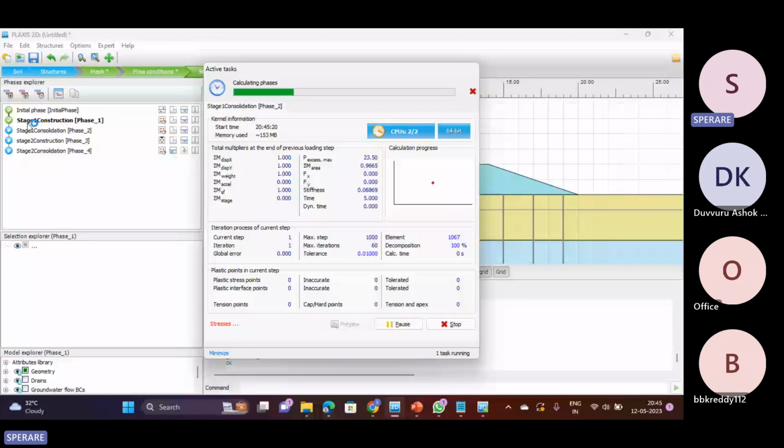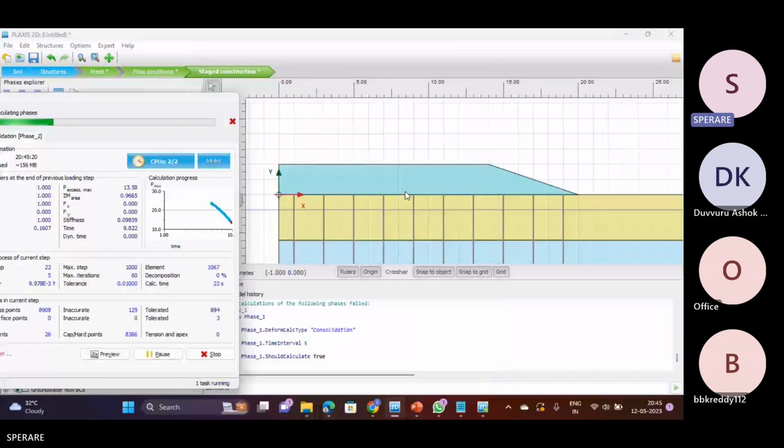So in the first case, during the construction process, I considered the entire block or structure of sand as a plastic calculation. The software assumes that this entire thing is a prefabricated one, and you are putting it at a time onto the soil.